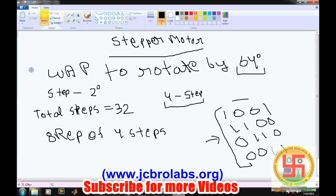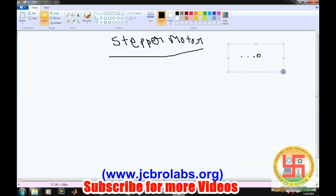This 4-step sequence was for rotating in full steps. Similarly, there is another way to do a more precise operation, that is the half step sequence. Half step sequence means that in one step the motor will rotate by half the step angle. So this is known as the half step sequence.